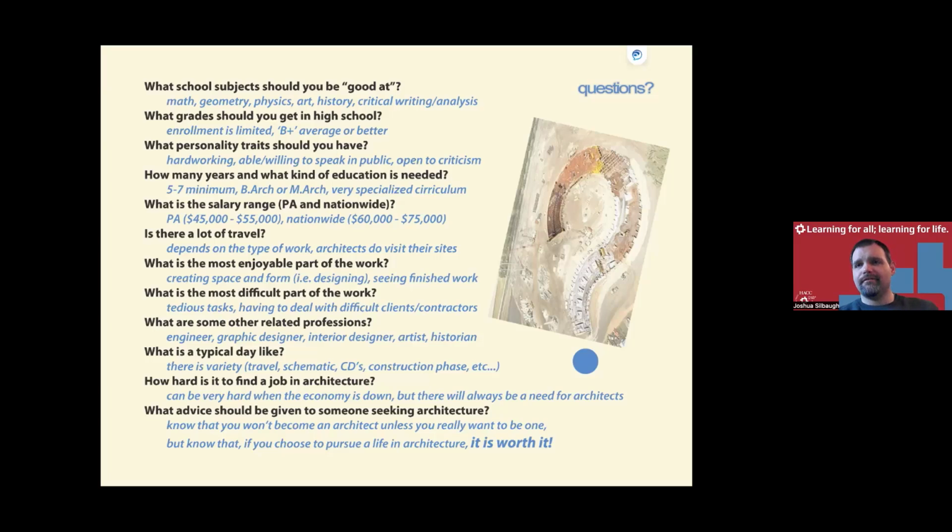There are foundations that absorb seismic events to limit the transfer up to the building. And with the way frames are designed, and the code requires a certain level of this, there are what I think are called dog bone frames, where essentially parts of the frame will fail. They absorb all the earthquake loads and fracture, which sounds like a bad thing, but they fracture and absorb all of the stress so that the rest of the building doesn't get it. It's like a sacrificial thing. So there's all kinds of things that go into the way buildings are designed to absorb them.